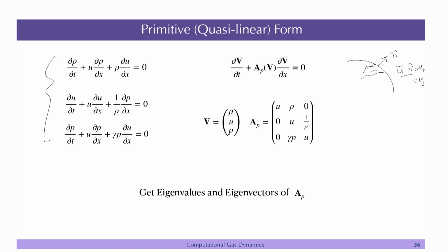Then you think of it as a locally 1D flow, where this is the flow and there is a normal here and u dot n is passing through it. So, this is locally 1D flow. So, write the 1D flow equations here. I will also show what happens to the other velocity components. Let us say you have v and w also, the tangential components, which you can call ut1 and ut2.